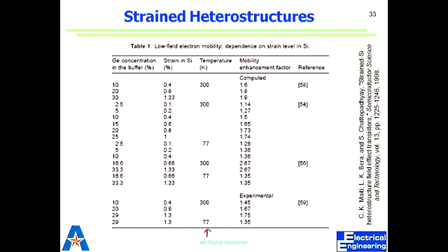So strain heterostructures, depending on germanium concentration, give you a mobility enhancement factor. So it's 1.6, 1.8, 2.67 even, right? And there is a strain in silicon also. Just look at this, just 0.66 percent strain, less than a percent strain. You get almost 2.67 times enhancement, right? So do you understand the importance? Why do they do the strain heterostructures? You can increase the mobility.